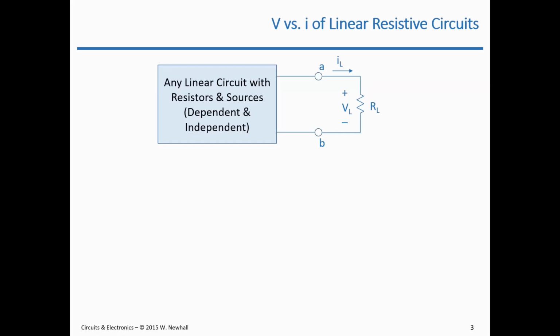And so we care about this because there are a lot of practical circuits out there that behave like this and are characterized by this, and it makes it easy to connect the right speakers to the right amplifier. And we'll talk about that when we get to maximum power transfer. But for example, your stereo output, your audio amplifier output that goes to a speaker, within a certain frequency range, it actually looks like a linear relationship between VL and IL if you vary RL.